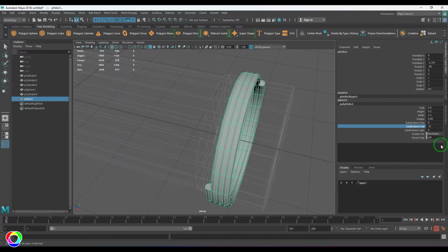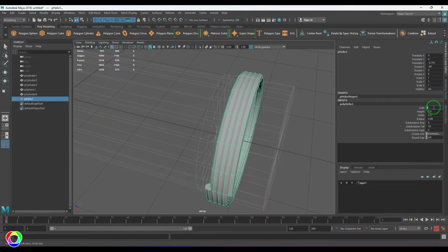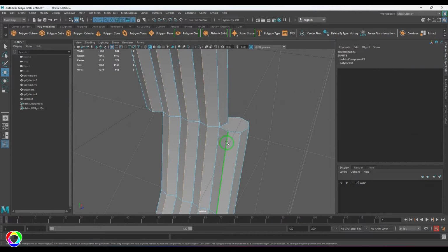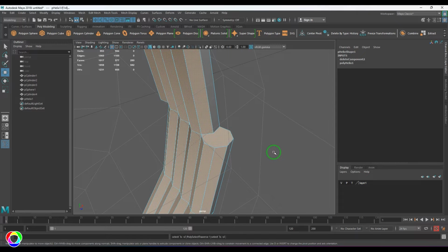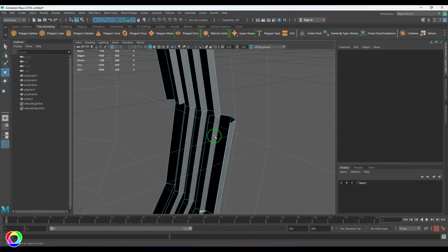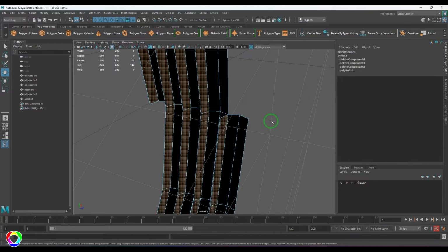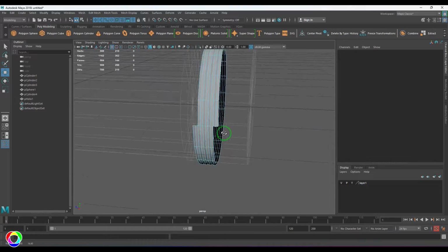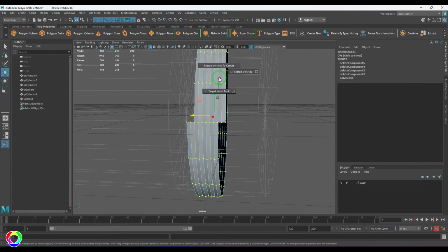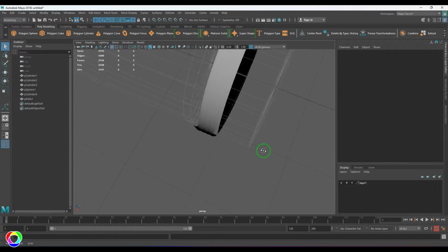So now the first thing is like the coils. We have let's say 4 coils, or maybe 5 coils, whatever. So once that is done, we can start working on these values like that. I'm going to select the face and then grow the selection till there and delete them, and this line I'm going to select it through the ring and delete that face, and I'm going to select this ring here and delete that face, and this should give me the spiral cap effect. So I'm going to select all that vertex points, and then I'm going to merge it like that. Now when I apply smooth, and this is what I should get here.